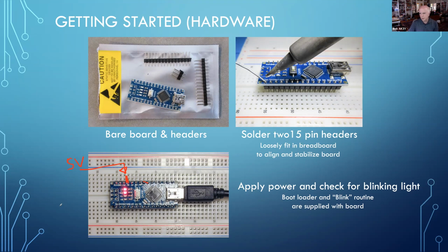I don't necessarily want to control it by USB or power it by USB. I may have a 12-volt supply that's already built in. I just put a 5-volt regulator chip in there and I'm up and running.